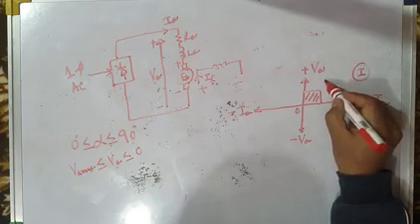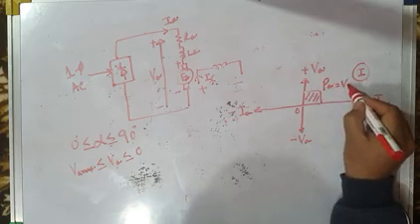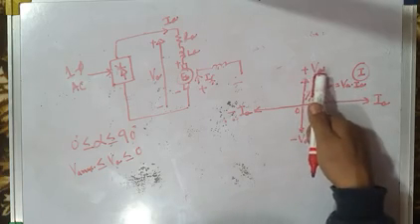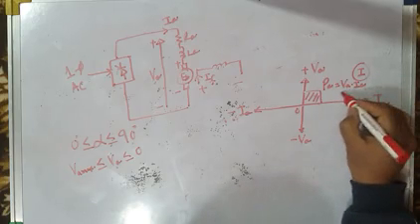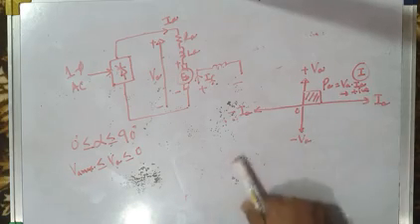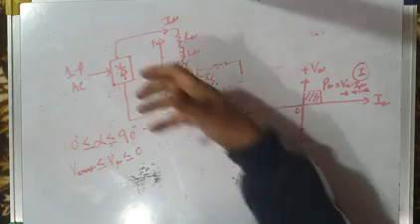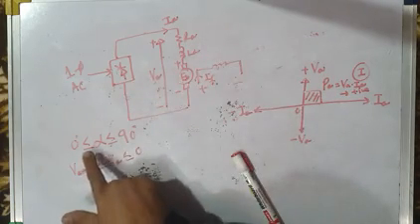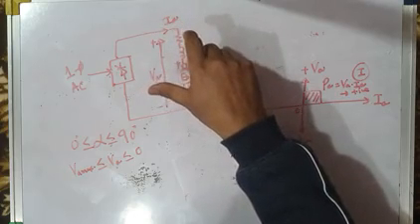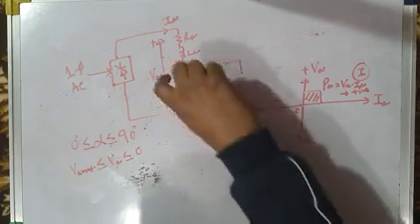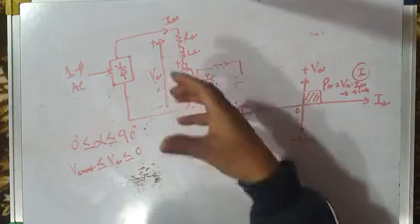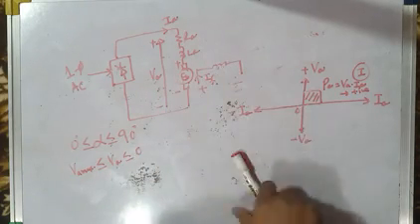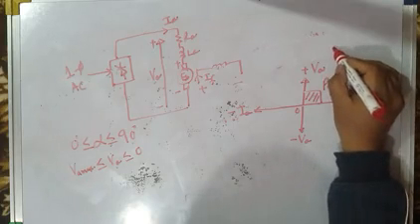And in the first quadrant, what is the armature power or motor power? It is average armature voltage into average armature current. Since average armature voltage is positive, current is also positive, so this is positive. Positive power means that your machine is operating as a motor. As a motor, it is drawing electrical power from the source at any value of alpha from 0 to 90 degrees, converting that electrical power into mechanical power and driving the motor and its driven load. That mechanical energy is absorbed by the mechanical load. So mechanical power drives the load. This is forward motoring mode.